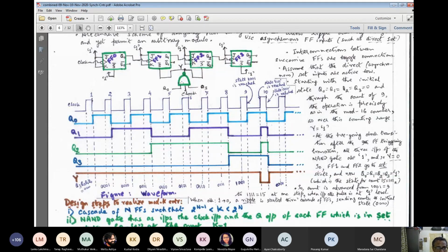So compared to the delay through FF0, remember, if the JK flip-flop is a master-slave flip-flop, the signal will pass through no less than 4 gates. Whereas here the signal is passing through only one NAND gate, and after that maybe it is directly connected to the final NAND gate. So here the signal propagation is through 2 gates, whereas there it is through 4 gates, right? So definitely the set input's effect will be annulled.